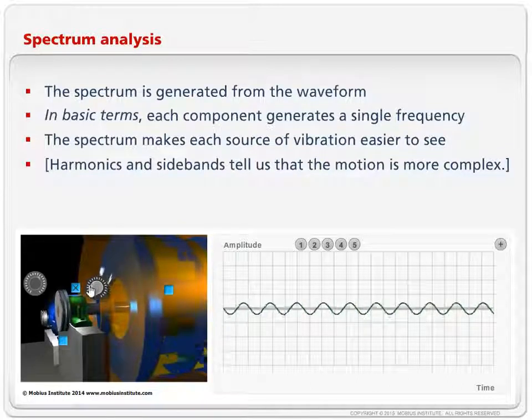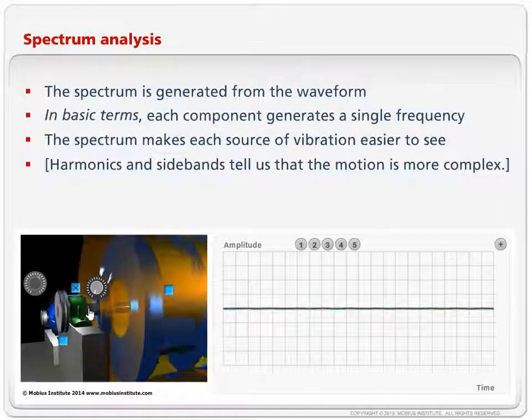Now, if the bearings were in tip-top condition, very good condition, I actually don't expect to see any green vibration, but as the problem develops, I get more and more green vibration related to the bearings. Let's turn that off for a second.